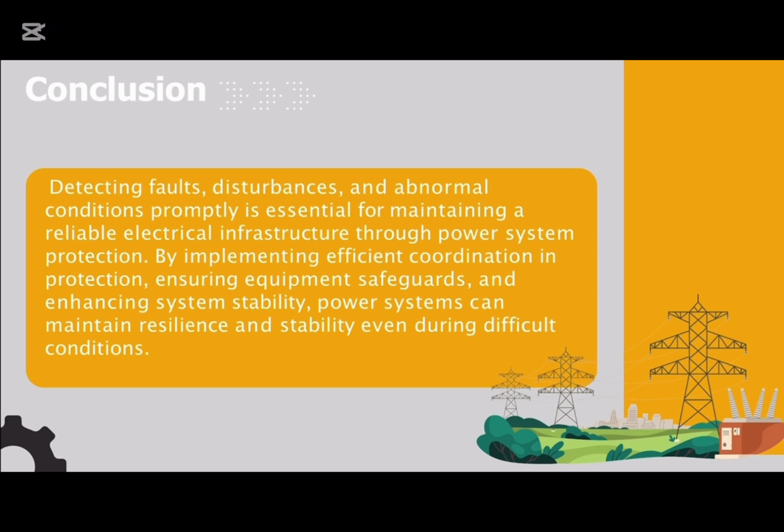In conclusion, our project was about designing a complete protection system for the IEEE 9 bus power network. We focused on protecting every critical part of the system: generators, loads, transformer, buses, and transmission lines. For each component, we applied industry standard methods using relays, CTs, VTs, and circuit breakers to detect faults early and isolate them quickly. This coordination between protection elements helps improve system reliability, reduce the risk of damage, and ensure smooth operation even under fault conditions.